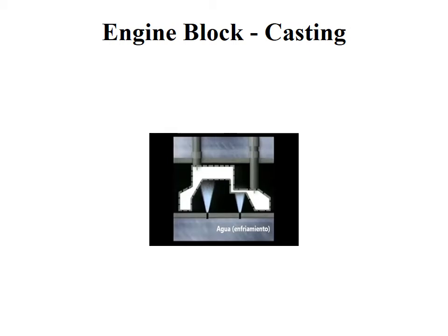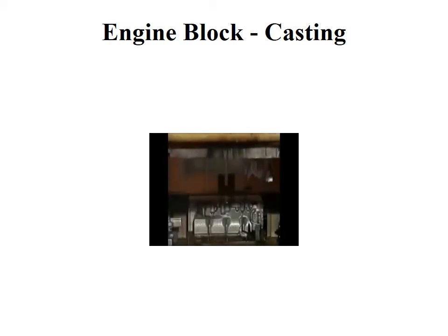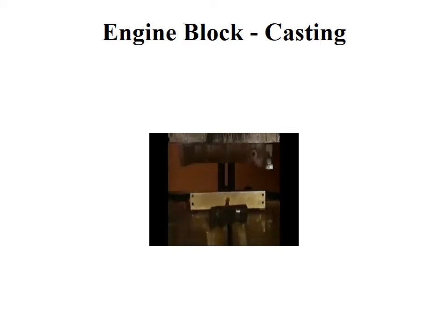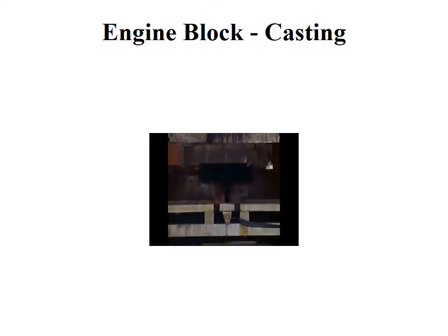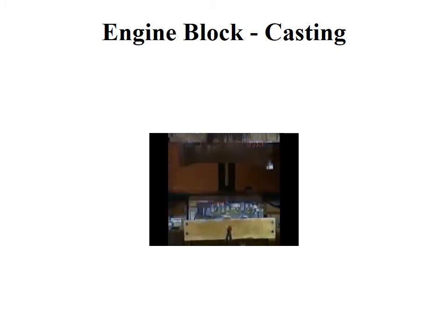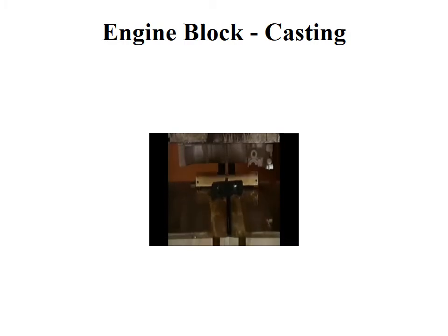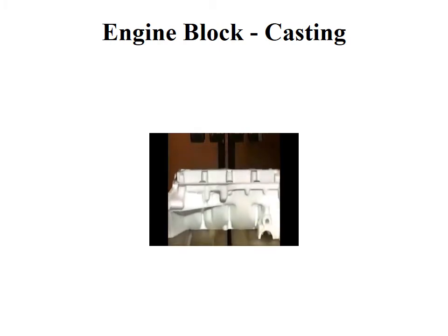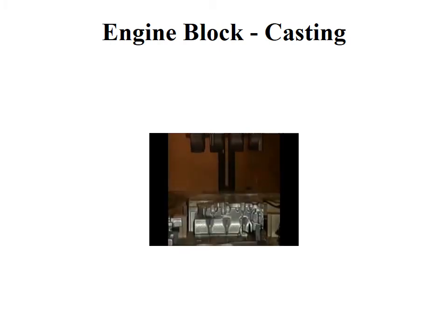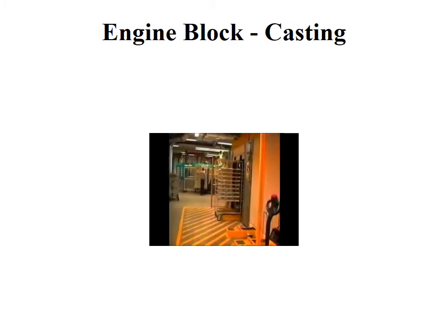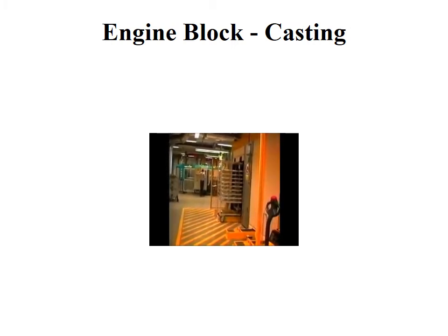the tool. Tooling is typically machined polished aluminum, producing very precise dimensions, and an unusual but smooth surface finish with precise detail. The tooling is exposed to only non-abrasive beads and steam temperatures, and usually maintains surface finish and original dimensional accuracy throughout an extremely long life. Foams are normally aged, usually in a controlled warm air oven, to stabilize the dimensions.